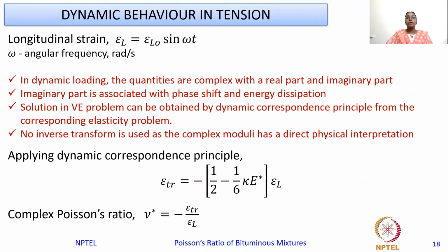So in the case of a dynamic test, again, the solution in the viscoelastic problem can be obtained by the dynamic correspondence principle from the corresponding elasticity problem. But in this case, you don't have to do any inverse Laplace transform, because the complex moduli that you substitute in place of the elastic moduli will have a direct physical interpretation. We will see what that is.